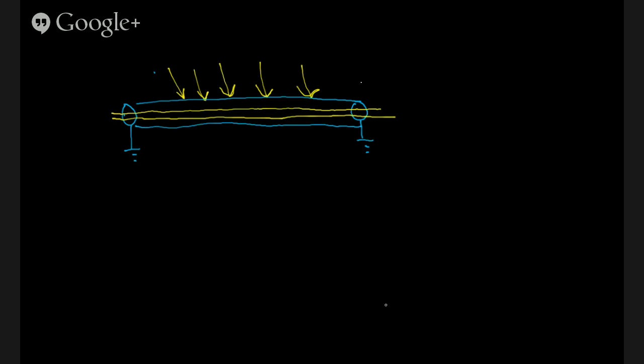But since it is conductive, sometimes we can have RF energy seep out from, say, our transceiver and conduct through the shield and into the microphone, which can cause some noise issues.